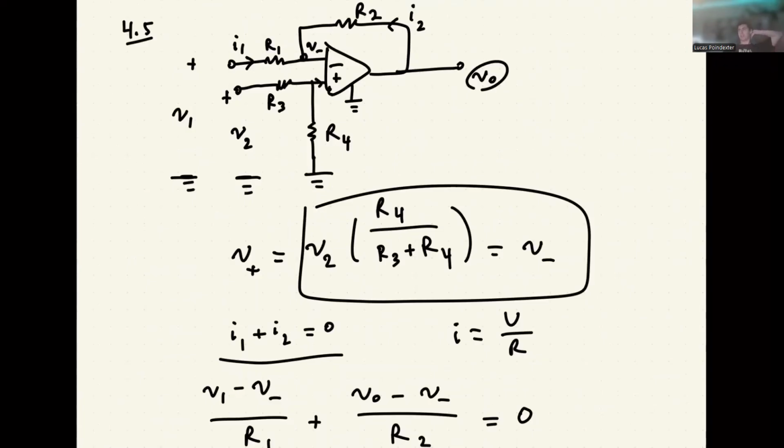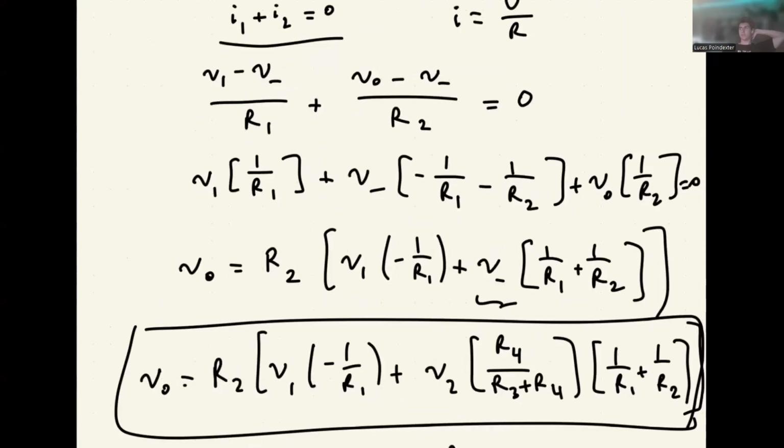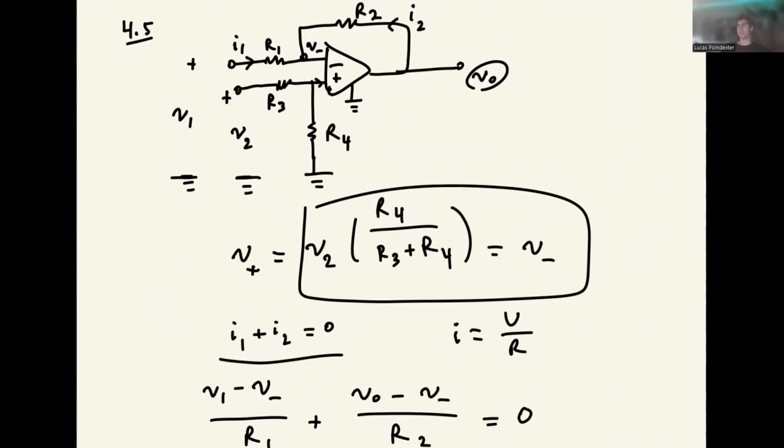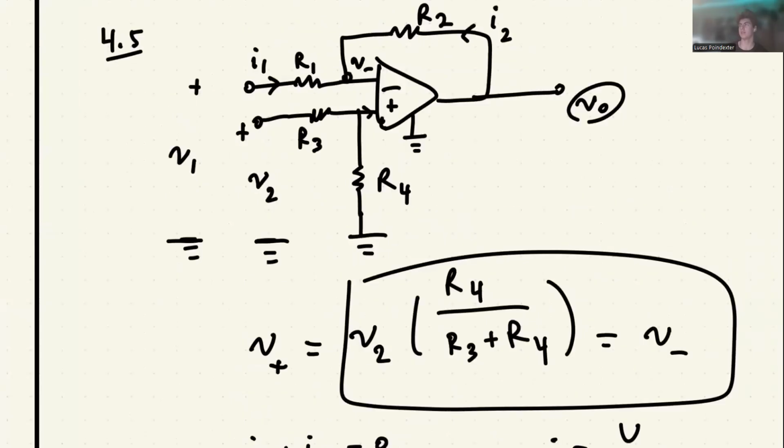Yeah, what's up? I also noticed that you had a ground symbol hooked up to the positive power supply. Is that because the negative power supply would be negative voltage? Oh, sorry. Yeah, it's kind of weird how they drew it, but whenever they've got the lower thing, that's for my negative supply problems, usually. But I mean, there's nothing really stopping you from connecting the positive supply to ground and the negative supply to a negative source. Okay. They've just drawn it like that for some reason.